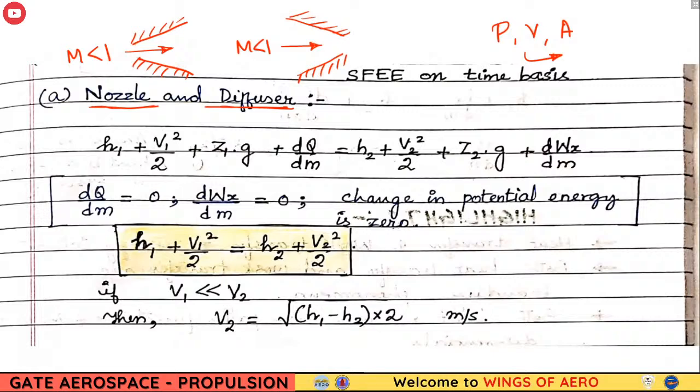That's why, with Mach number less than 1 and a convergent nozzle, we get an increase in velocity. That's the example I gave: in a gas turbine, they use a kind of convergent nozzle. In a rocket, obviously they use convergent-divergent.